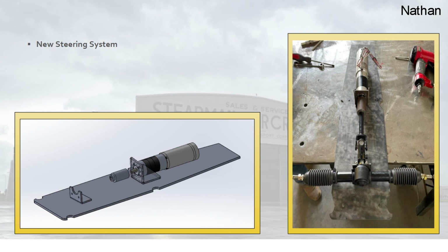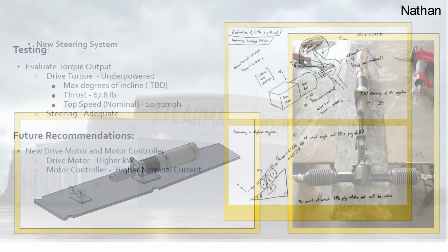The drive shaft then connects to a spline on the rack and pinion, and that rack and pinion turns the wheels. The rack and pinion is held in place via that little angle iron piece you can see in the bottom left corner. We've added C-clamps later to prevent any sliding of the rack and pinion left to right. That became more of a concern as we later on realized how much torque that rack and pinion is undergoing.